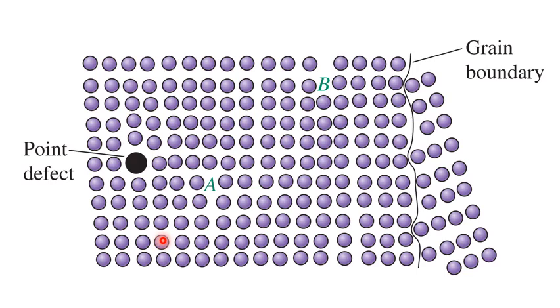For example, here we have point defects in this structure, and we have the same dislocation A. When dislocation A, under external stresses, moves to the left, it will encounter the point defects here, and it needs higher stresses to pass through this area, because the point defects introduce imperfection in the solid.